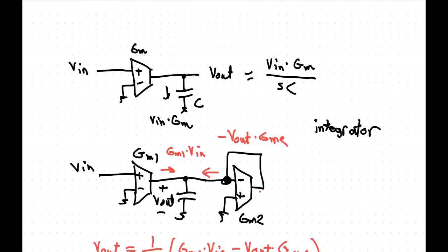Yep. If we have multiple poles to make the low frequency band very sharp, so these three filters should have no coupling capacitors, right? Just isolate that. Otherwise, it becomes a whole system. Well, it depends on what you know. If you put coupling capacitors in between the stages, you get a band pass. Because these 3 poles should be set at the same frequency? No. Not at the same frequency.